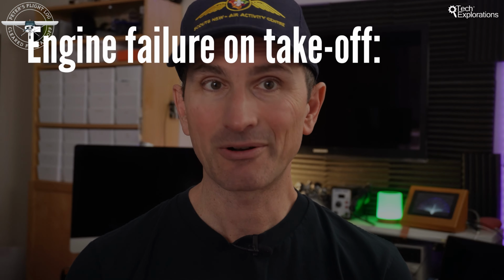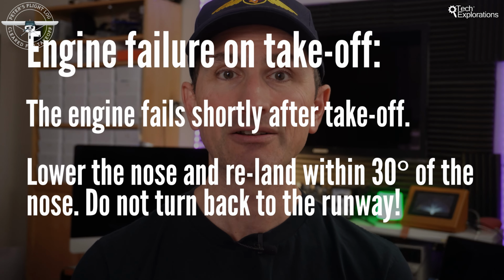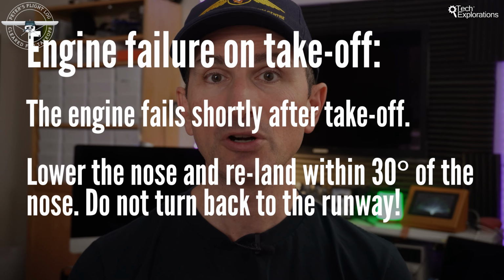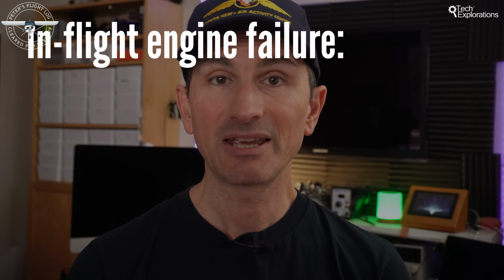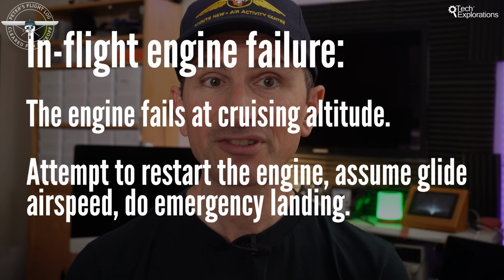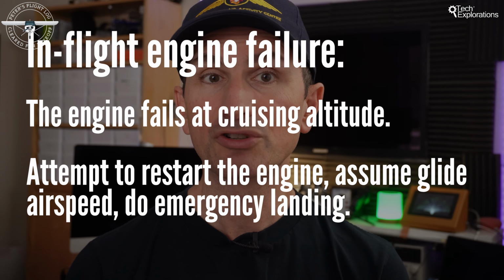Engine failure on takeoff. In this situation, the engine fails shortly after the aircraft has taken off but hasn't gained much altitude. The standard procedure involves lowering the nose to maintain airspeed and execute a forced landing straight ahead or within 30 degrees of the nose's direction. In-flight engine failure. Here, the engine fails while the aircraft is at cruising altitude. The first step usually involves attempting to restart the engine. If that fails, the pilot looks for a suitable area to perform a forced landing.